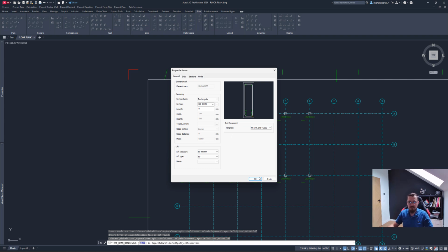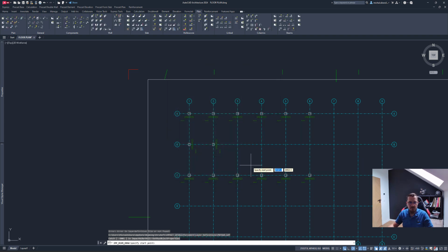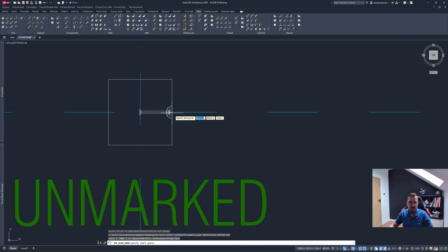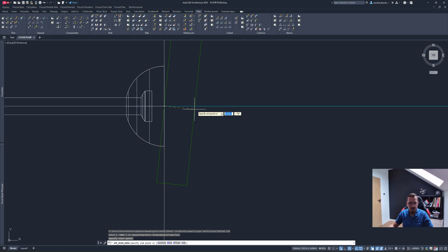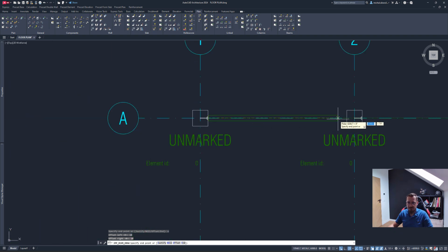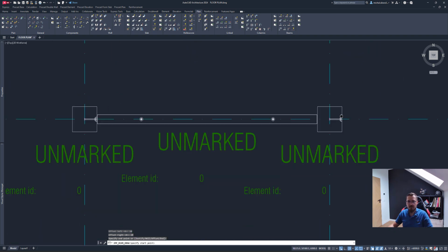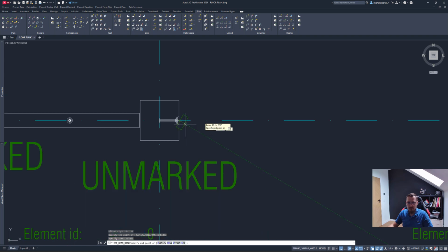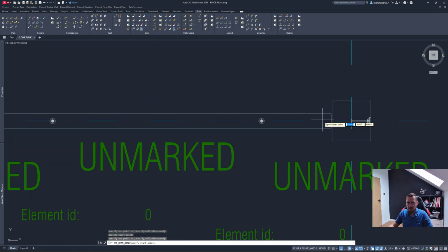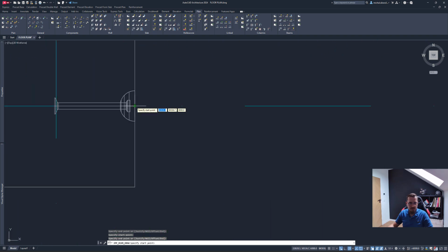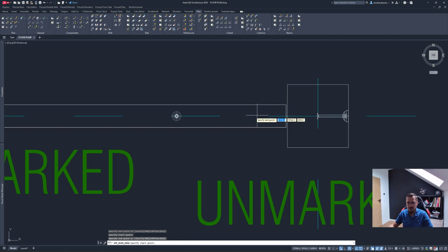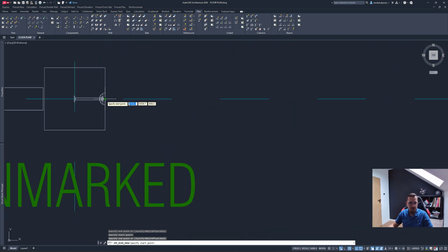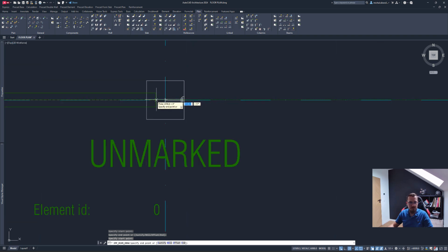I don't really want to modify anything else in this particular scenario. So I want to specify the first point here. I also want to apply offsets, so they're not exactly flush with the columns, because that's offset left and now offset right. And as you can see, we are now offset with the beams. Leaving those elements flush is not exactly perfect. Simply put, it might be hard to place those elements on site if they're flush, or we might crack some concrete or do something we don't really want to do.